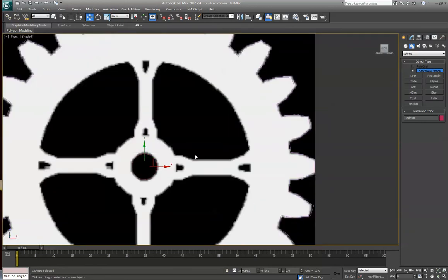So now I'm going to look at some of these bigger areas in here. So I'm going to go back to using the line tool. Now, like Photoshop, if you click and drag while you're using this line tool, if you just click point by point, it's just going to create straight lines. But when you get these curves, I can click and drag, and you can see that it curves the line. Now again, this is something we can go back and edit, so I will do that. So again, here's a nice curve, so I need to click and drag.